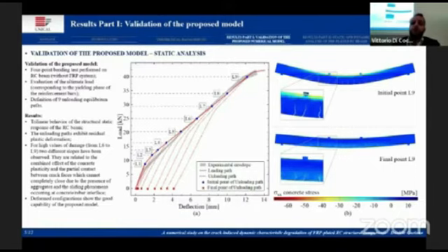For higher damage levels, for example from L6 to L9, we can see that each curve has two different slopes that are related to the combined effect of the concrete plasticity and the partial contact between the crack faces, which cannot completely close due to the presence of aggregates and the sliding phenomena that occur at the concrete-rebar interface.